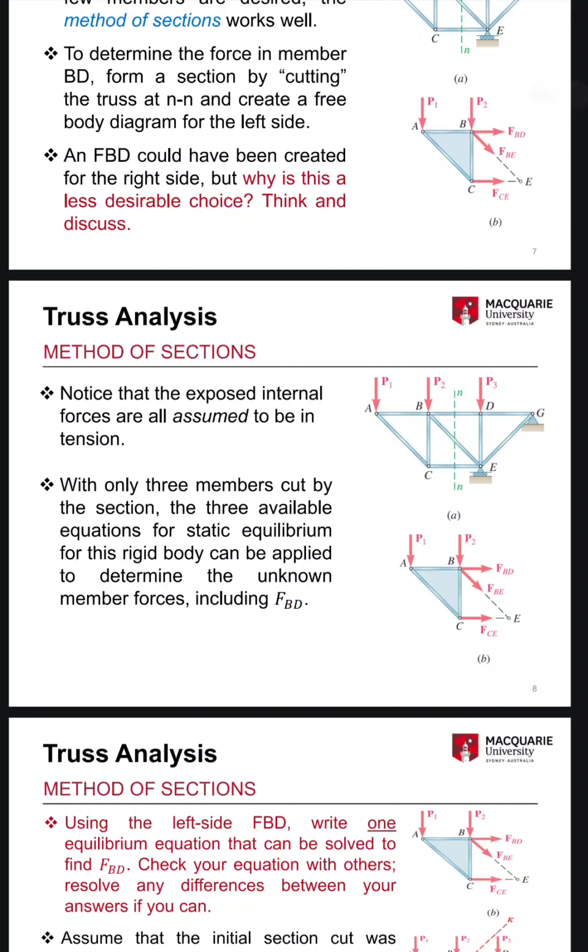Truss analysis, method of sections. Notice that the exposed internal forces are all assumed to be in tension. With only 3 members cut by the section, the 3 available equations for static equilibrium for this rigid body can be applied to determine the unknown member forces, including FBD.